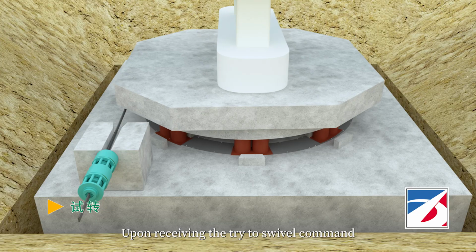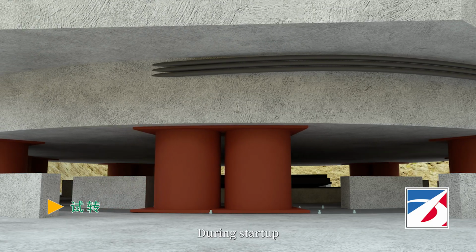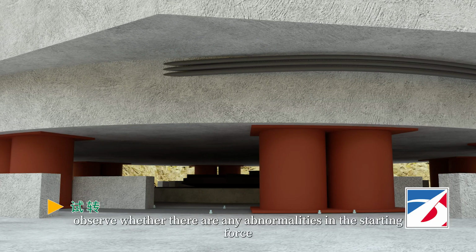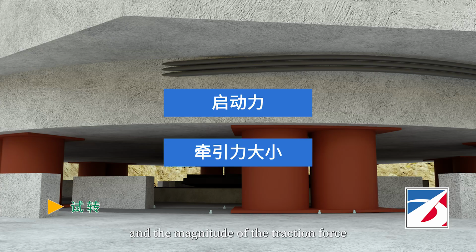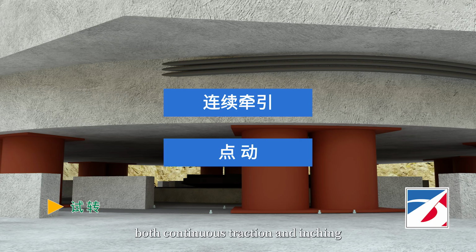Upon receiving the trial swivel demand, commence the test run. During startup, observe whether there are any abnormalities in the starting force and record the starting force and the magnitude of the traction force during the swivel process. The trial swivel should include both continuous traction and inching.